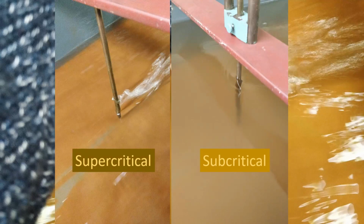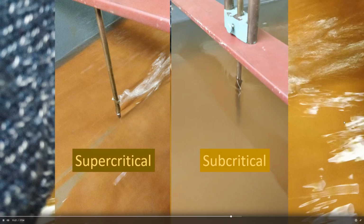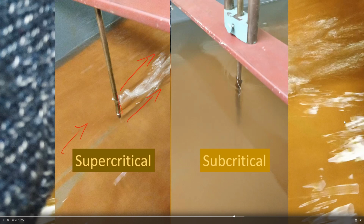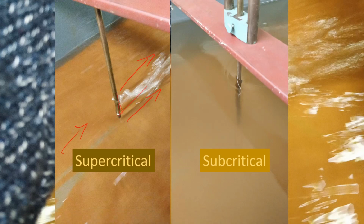Okay. We were thinking about subcritical and supercritical flow, and these pictures enable you to just realise what's happening. In supercritical flow, all the information, all the waves are flowing downstream. They're going back, they're going that way, so the flow is this way, and everything is going downstream. So you put something in the channel like this measuring device, and it only affects everything downstream.